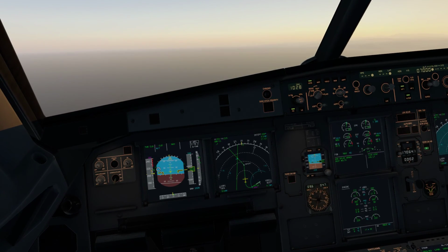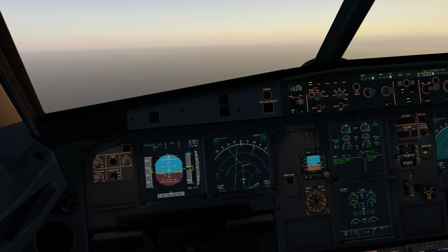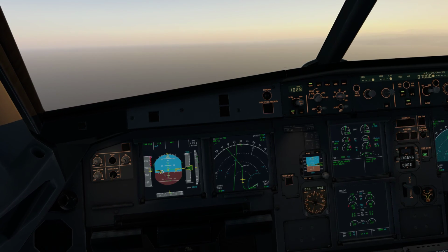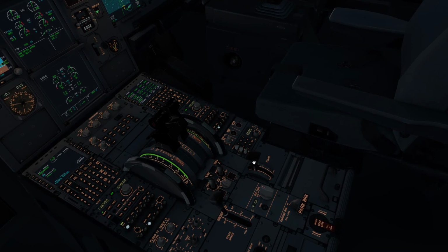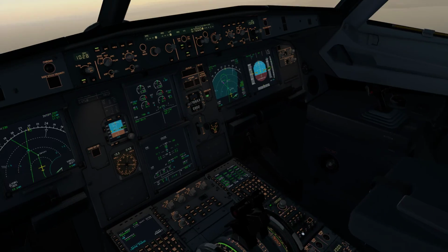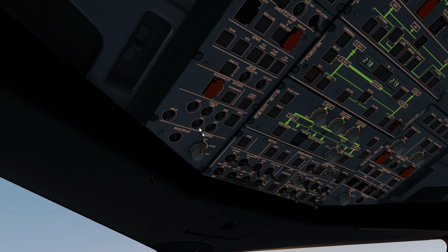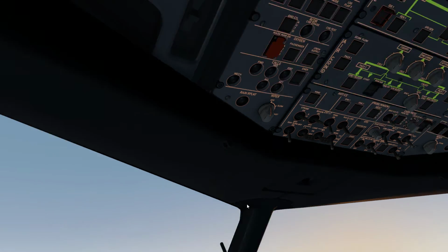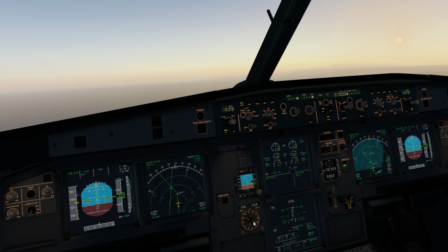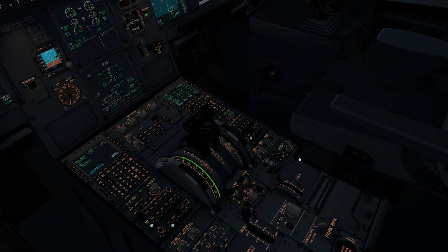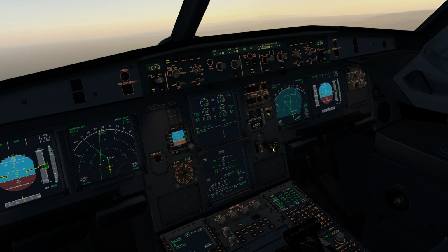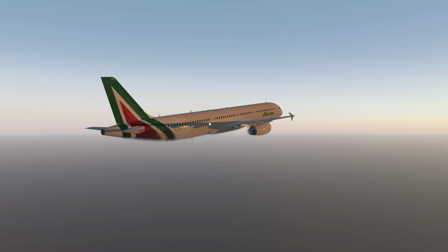And as soon as we reach the airspeed, we can go flaps up. Okay, flaps up. Put back the spoilers. And inform the cabin crew that they can move around. Turn off the runway lights. Oh, and one thing we forgot to do. TCAS on TA/RA. Oh well, that's how it is.